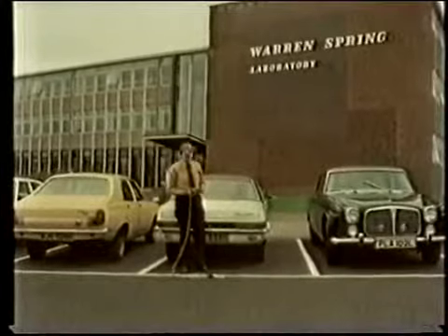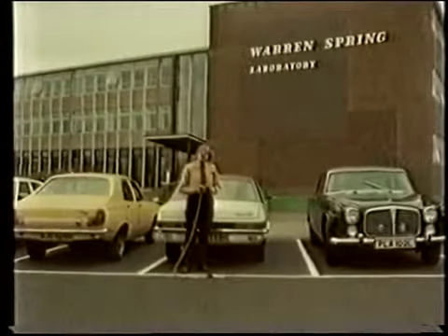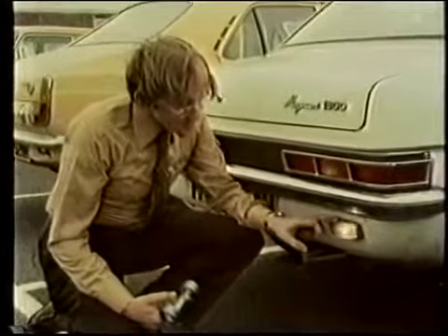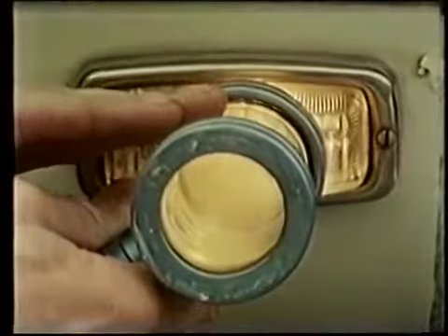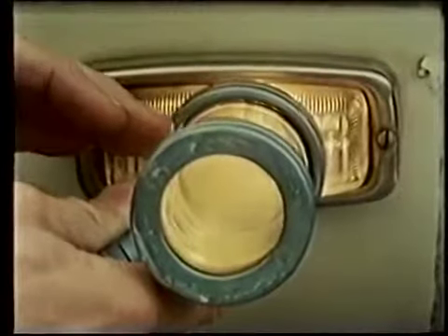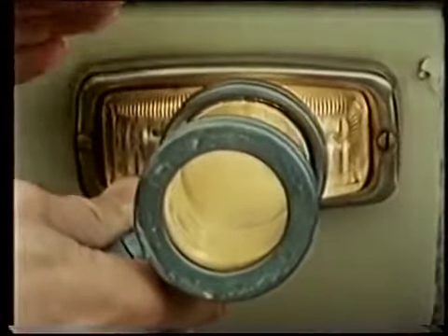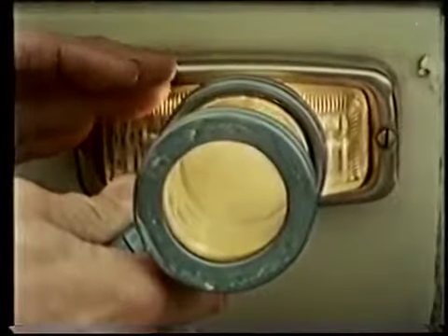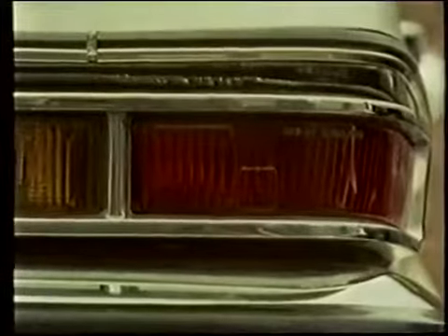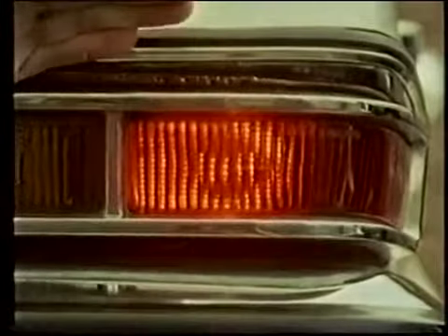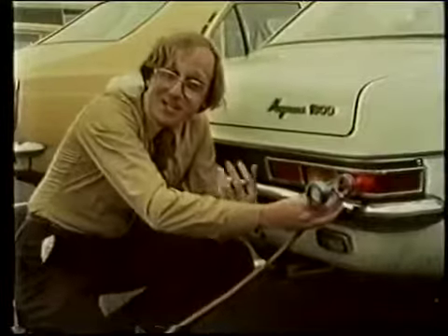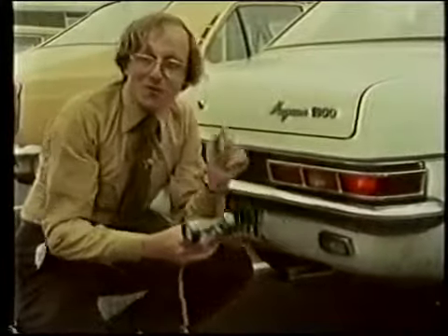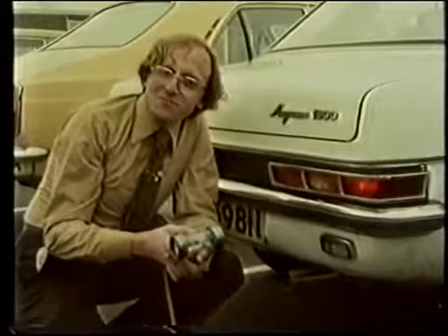The idea behind this method of analysis is rather simple. What they do is they take a light source and shine it through the cell. Now, by measuring how much of the light is absorbed in the cell, they can work out what gases are present and in what proportion. In fact, if we just use white light, nothing much is absorbed. But what happens if we use red? Well, in this particular case, not much is absorbed either. In fact, to get a substantial absorption, we've got to go way beyond the red into the infrared region.